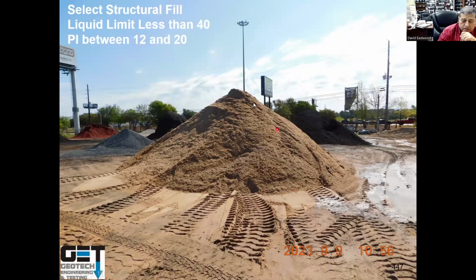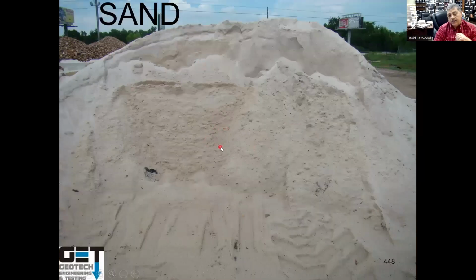Is the select fill. That's what you put on your slab in your forms. Liquid limit less than 40, PI between 12 and 20. You don't put sand in it. Don't put sand in your forms because water travels through sand and gets to the expansive soil and causes it to heave.